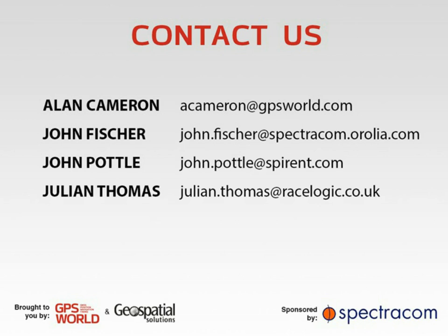Now, there is a thing that it might dilute precision by doing that. It actually doesn't necessarily make it more accurate, because, again, of these differences across the systems, but you might get accuracy. So the measure of accuracy is an important challenge when you have multi-constellation, because the real advantage of multi-constellation is availability, that you can see more satellites. So when you're in shadowed areas, that's really where multi-constellation has its benefits.